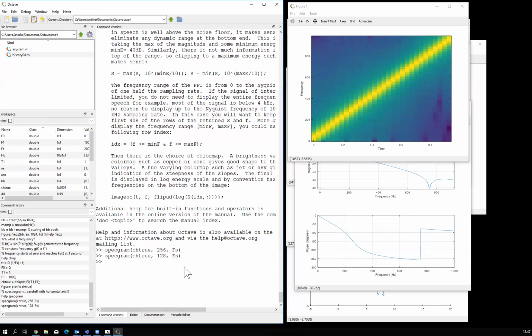So this is a signal representation in the frequency domain. We have the time going horizontally and frequency going vertically. Now be careful when you are using MATLAB. There's a spectrogram which gives you time on the vertical axis, which is not wrong, but it's awkward. Nowhere else in any culture do you have time 0 at the lower left corner growing up. I would understand it if it was a waterfall plot where time 0 is at the top left corner and time flows down, the same way as you read text, starting from the top line and going lower, but not the way MATLAB has the default.